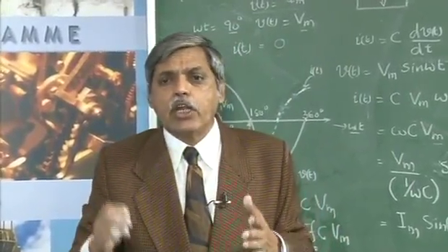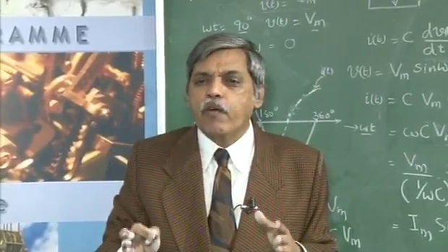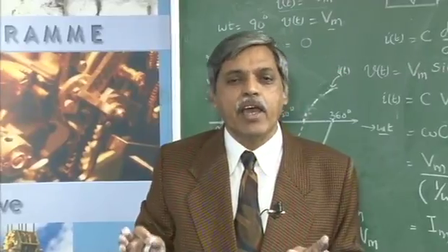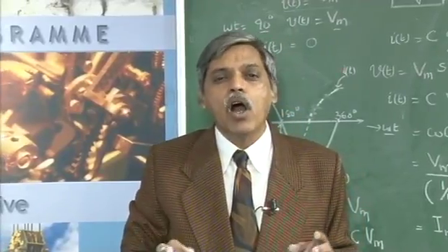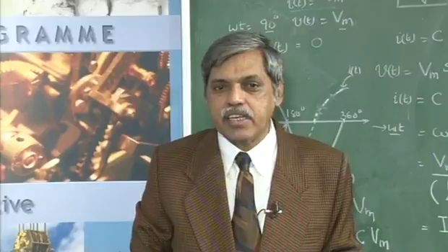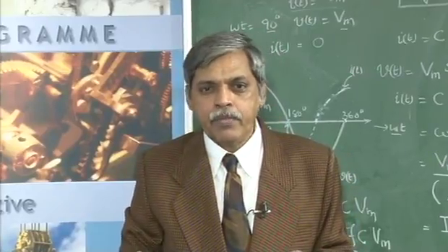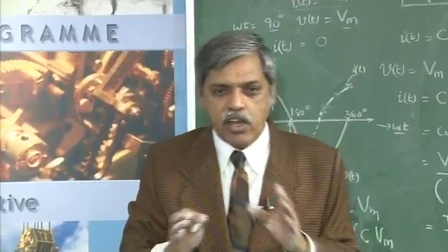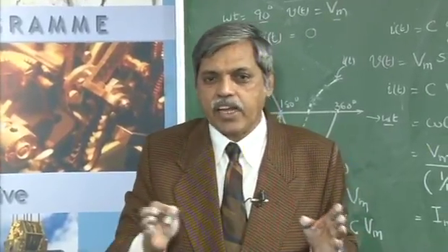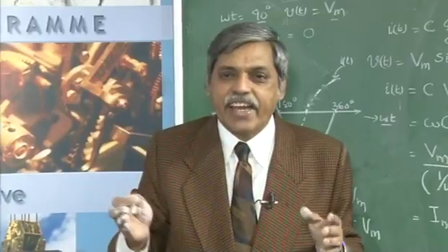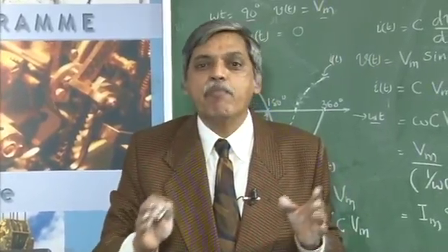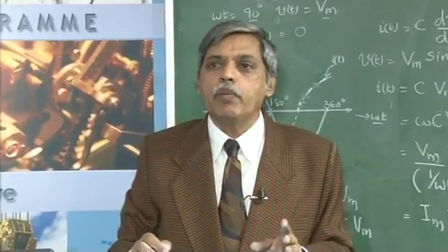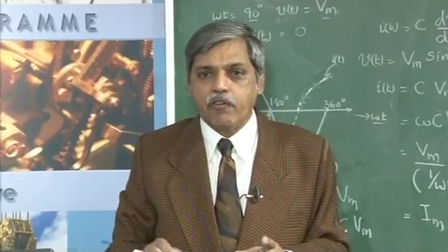To tell you directly, in all circuits where the elements are connected in series, I will take the current as the reference quantity, because all elements connected in series carry the same current. If a resistor, inductor or capacitor are connected in parallel, they share the current, but they carry the same voltage across them. Because of that, in parallel circuits we will take the voltage as reference.